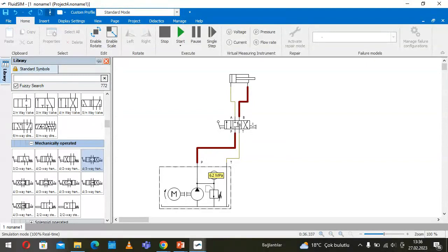So then if I start to move forward, and if I stop or change the position of the valve, bringing the valve into the middle position, you see the piston is somewhere in between the two end positions. And if I operate once more, the piston will complete its motion in the advance stroke like this.